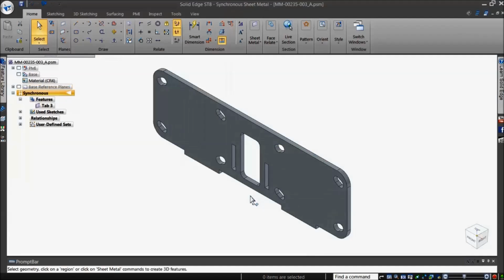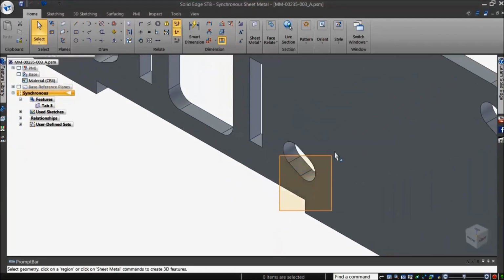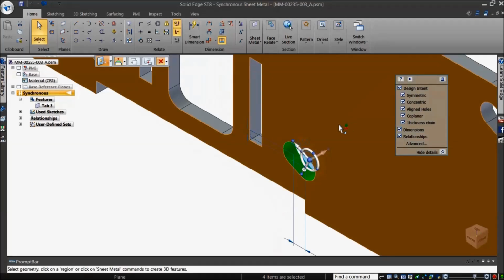The steering wheel can also be oriented in all X, Y, and Z directions. With the steering wheel in position, you can shift and drag the axis bearings. Additionally, when the focus is in the dimension edit box, key in a precise angle. After setting the first angle, drag again from the other axis to set the compound angle.